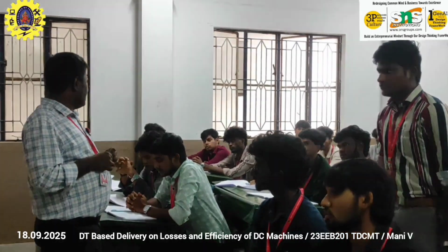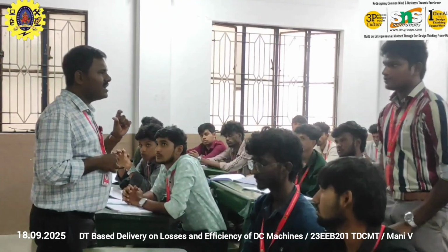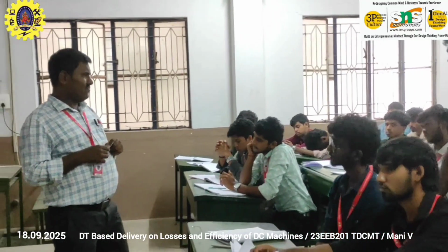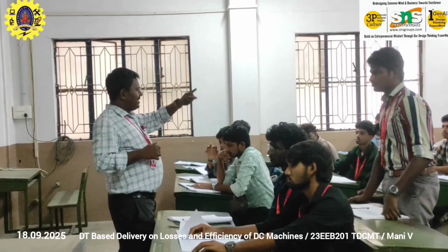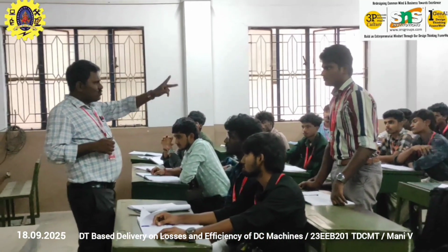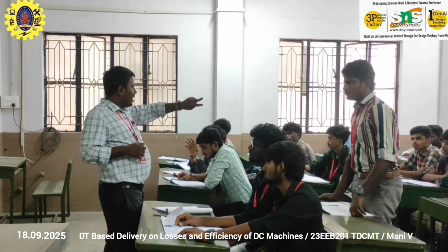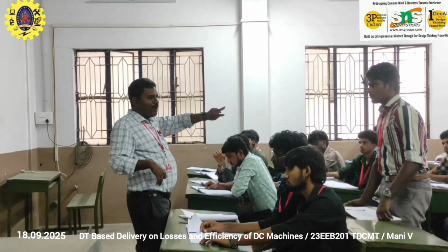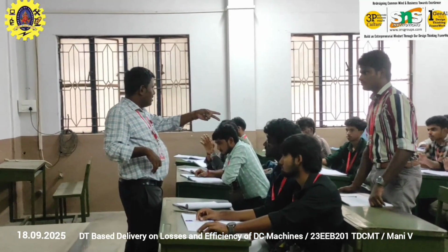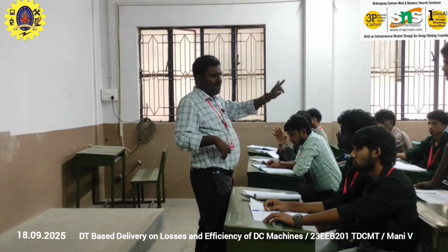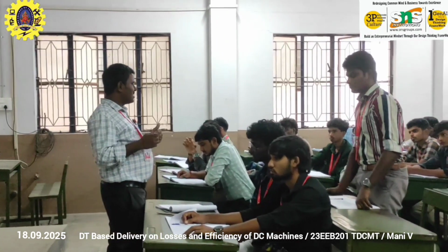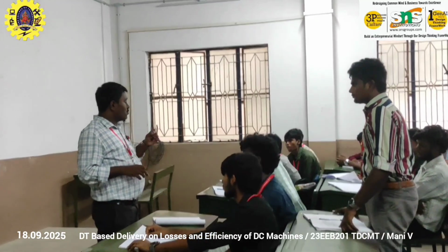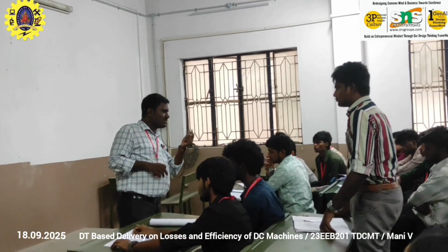It depends on the frequency of reversal of flux, because the north and south poles, the polarity, are always changing during the cycle. When the polarity reverses, the flux also reverses, forward, reverse, forward, reverse. During this reversal, some amount of flux gets lost. This is called hysteresis loss.